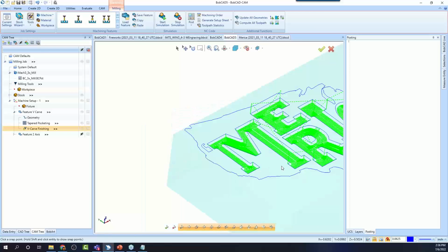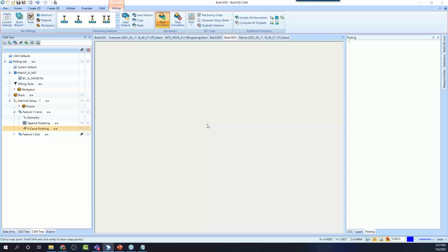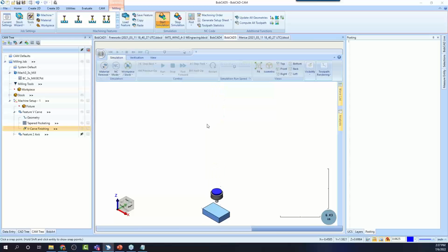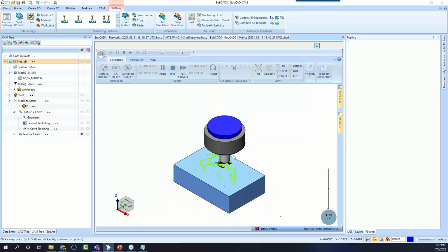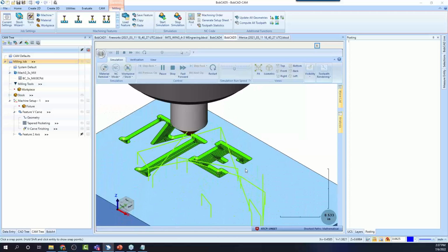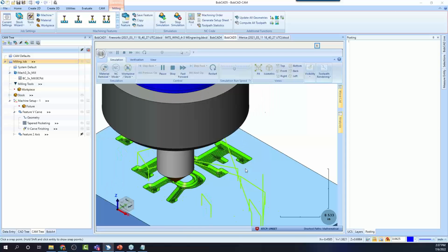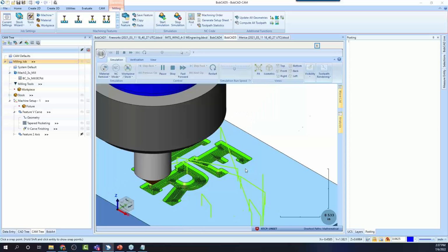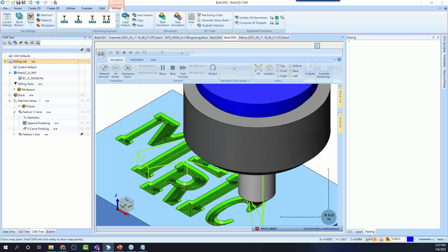Now, when you end up doing that, what happens is it'll give you a nice wall finish, but you're going to have a bunch of material being removed with that V cutter, right? And that V cutter, I mean, it does a good job, but it's probably not as efficient as if you could use an end mill to clean out the pocket and use the V Carve to come back and clean up the wall. Okay, so that's why you see two different operations here.